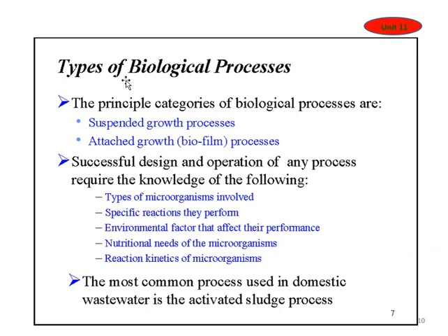Biological process is the aeration tank. The aeration tank is a place where we put all the wastewater in a big tank, and we provide the mixing of the air. Purpose of mixing the air is to add the oxygen in the wastewater. The more oxygen we add, the bacteria will grow and they will eat the waste material, and they will remove the waste material from the wastewater. Water will become clean. So there are two types of biological treatment processes. One is called the suspended growth process and another is the attached growth process.